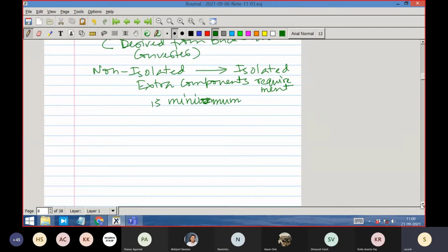It is somewhat popular for low power applications when you don't need anything more than 30-40 watt. This will be the first choice. If you need at least 100 watt, you may have to go to some kind of buck derived converter topology. So let us see the flyback converter. Let us one more time sketch the buck boost converter and see how it can easily be converted.